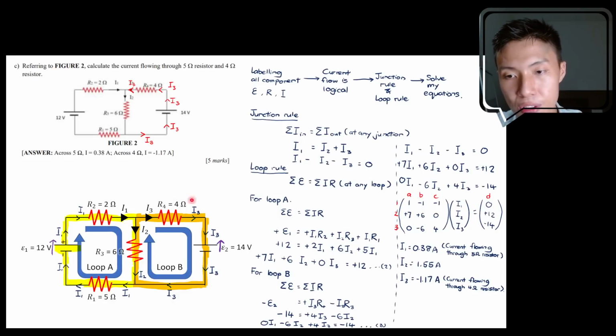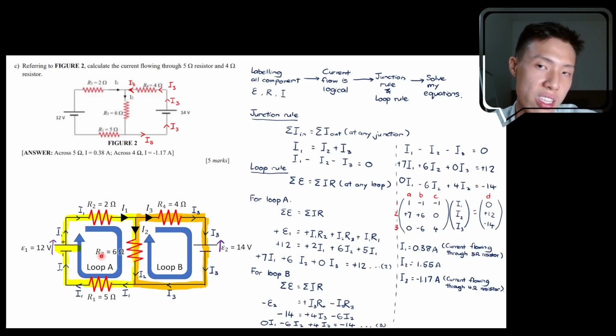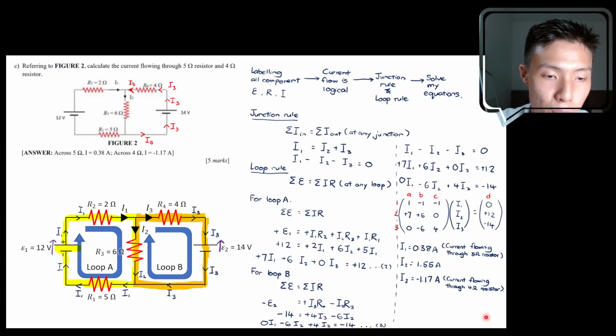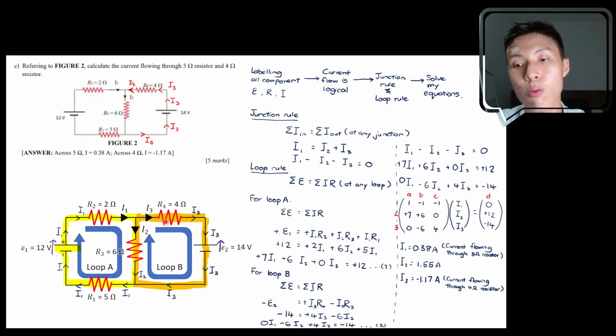Don't edit the first diagram that you draw, the first diagram that you analyzed. Don't touch anything about it. What you do is redraw the circuit diagram with the corrected direction of current. For those that are negative, you redraw the correct direction. After you calculate everything, at the bottom, you draw a new circuit diagram with the corrected direction of current.